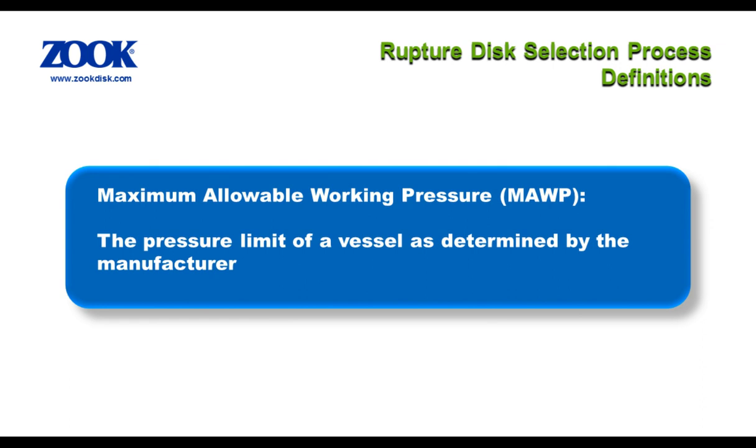First off is maximum allowable working pressure, or MAWP, defined as the pressure limit of a vessel as determined by the manufacturer. Any pressurized system that a rupture disk will be protecting should be rated with an MAWP. ASME, or the American Society of Mechanical Engineers, is the governing safety body in most of North America, and their boiler and pressure vessel code defines MAWP as the highest permissible gauge pressure of the vessel.